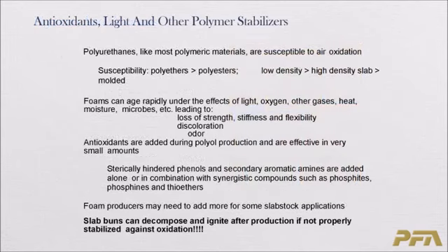Another important ingredient is the antioxidant, as I mentioned earlier. Typically, during the polyol manufacturing process, the manufacturer adds the antioxidant depending upon the end-use application. But if you're going to be trying to use a non-slab foam in a slab application, you need to make sure that the right antioxidant level is present by either measuring or adding additional antioxidants.